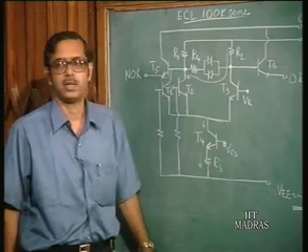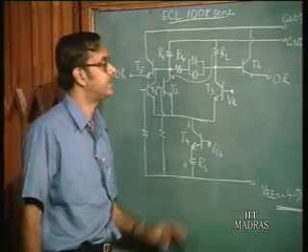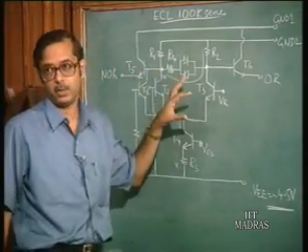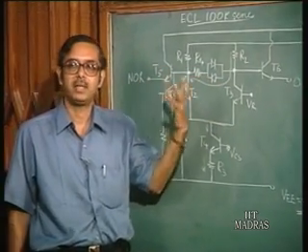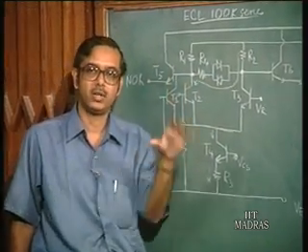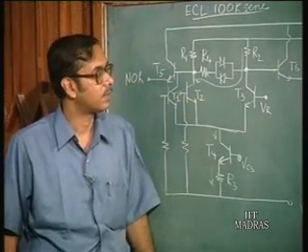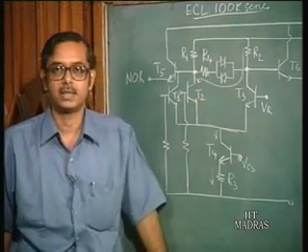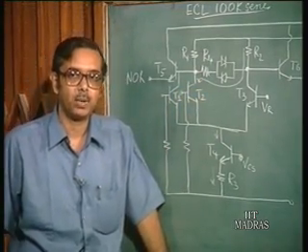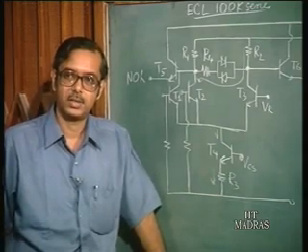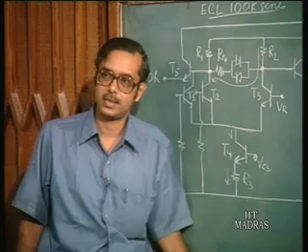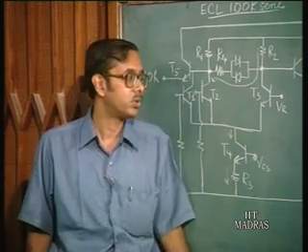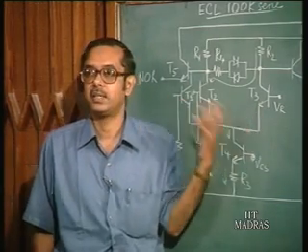The other major modification is, as I said, from the technology point of view. These transistors, as in the advanced TTL series also, are different transistors in the sense that mostly they employ oxide isolation instead of junction isolation, which reduces the parasitic capacitances from the device, and also the device dimensions are reduced.